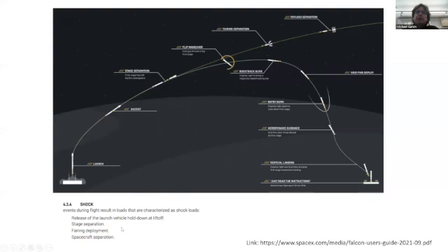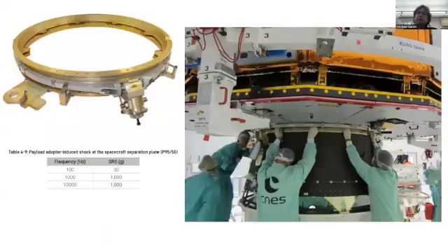And then one more typical high shock environment is payload separation. When the spacecraft, the final payload, is popped off the top of the upper stage. And this is often, although it's changing these days, often performed explosively as well with explosive hold down or release devices. So again, it can impart pretty high shock loads on your payload. So yeah, one of the most characteristic shock loads happens at spacecraft separation.